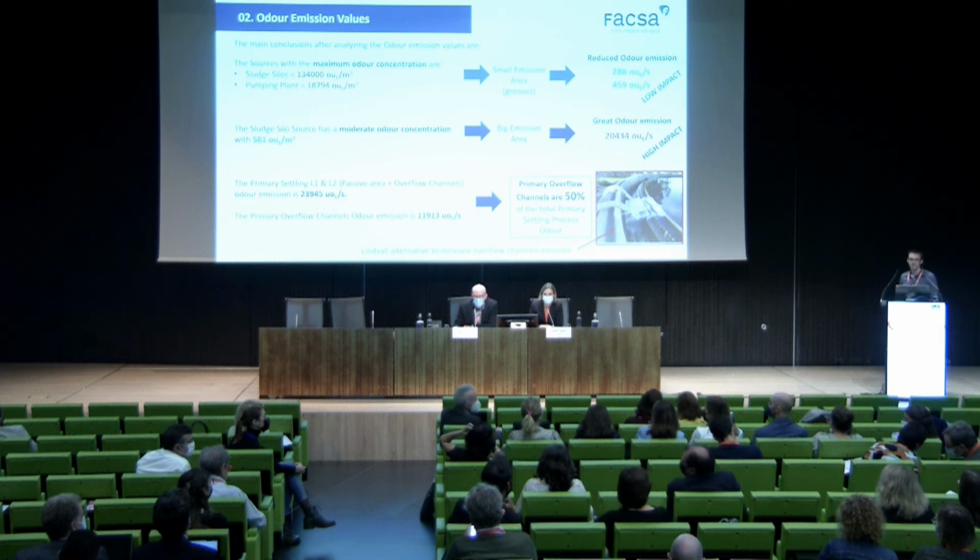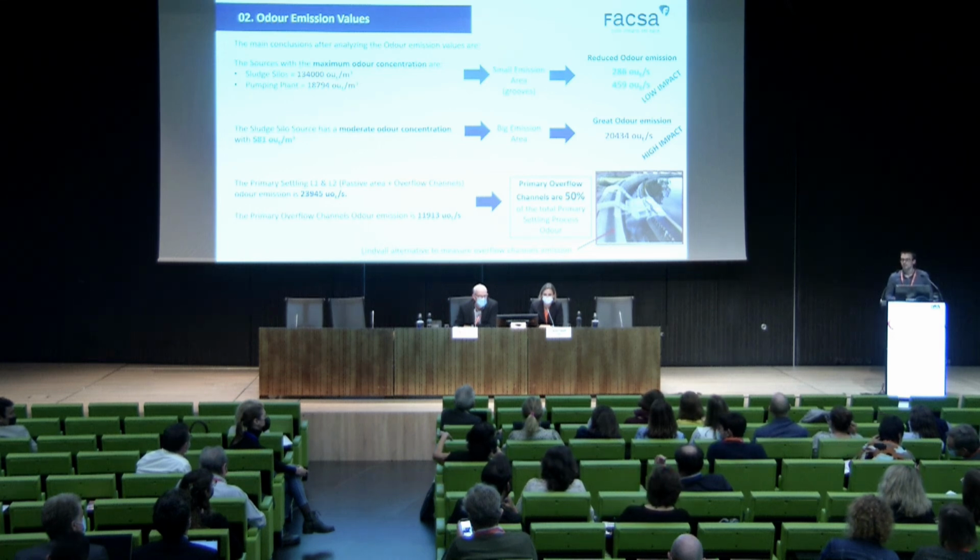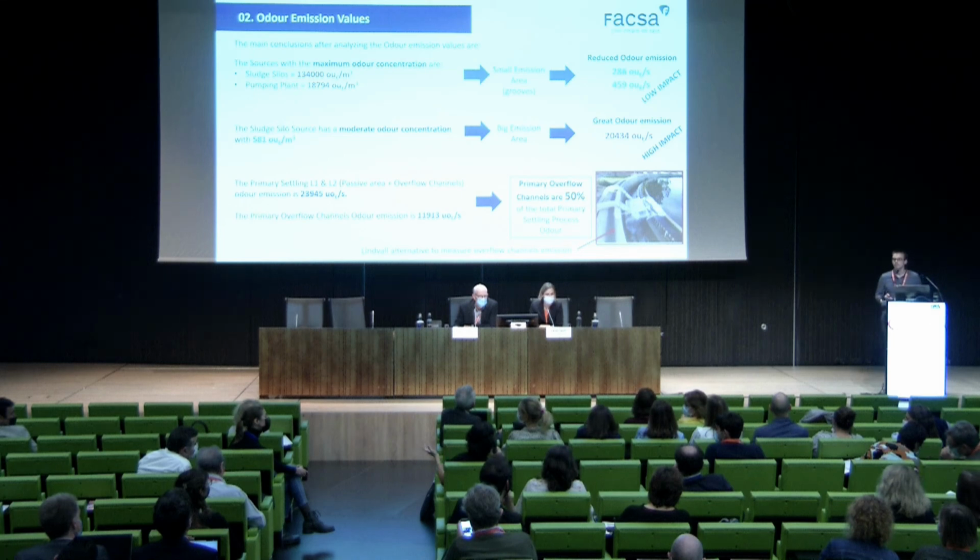I have a question. Perhaps I missed it, but when you calculated the reduction in odor after covering certain units, did you assume that you have 100% reduction by covering the facility? No, we calculated different percentiles with a CALPUFF model, and we compared the values with the current scenario. All the percentiles were compared with the current scenario, and we saw the reduction on the percentiles that we get.